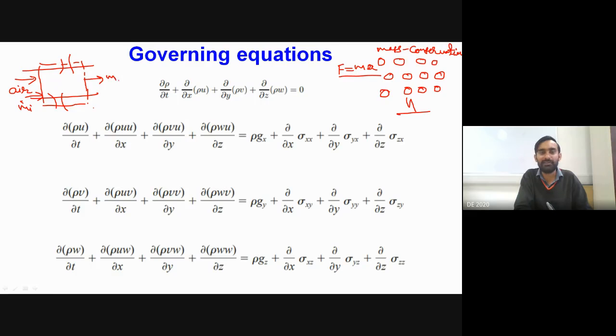and what outflow of fluid is actually happening from this, and we will find that m inflow minus m outflow will be equal to nothing but dm by dt. This represents the rate at which there is change in mass of the control volume. So this will be a mass conservation equation which will be very, very important while we are studying the characteristics of any fluid control volume.